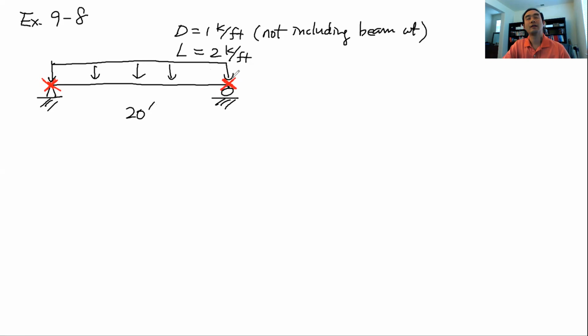So what it means is that we do not have any lateral support in between, but we do somehow have, going through an additional member connected to that beam at the support, or we could have a lateral bracing there, or a connected slab or something like that to prevent lateral torsional buckling in our compression flange, only at the support. So this information automatically says that our Lb, the unsupported length, will be equal to our L, which is 20 feet.